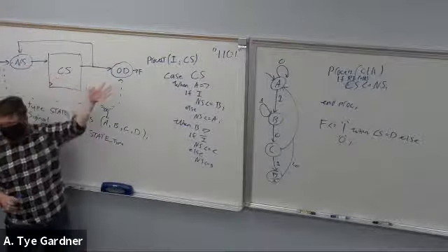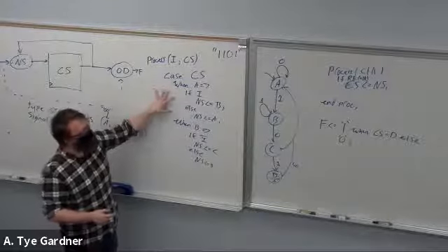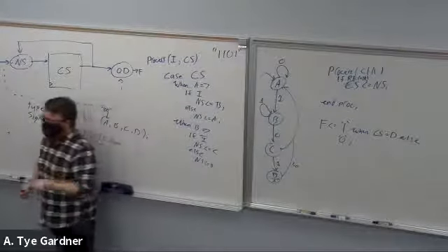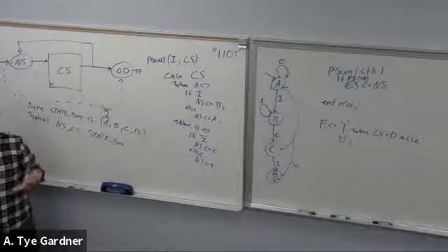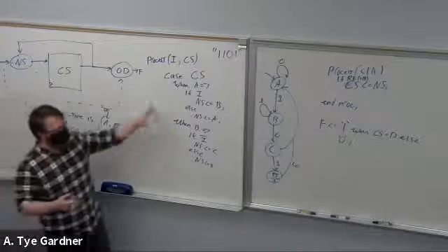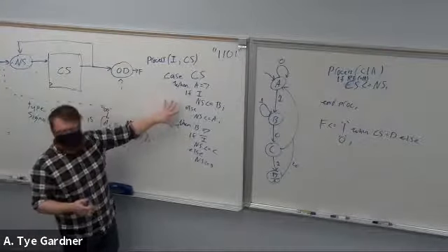You can combine these guys into sections of blocks, sections of code in there. So let's look at the process for the next state logic. It is easy to combine the next state logic with the current state. And in fact, this is what I encouraged you to do without being so explicit about it in the lab, because it's really easy in that we don't even need the next state logic